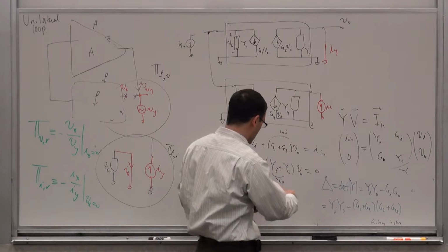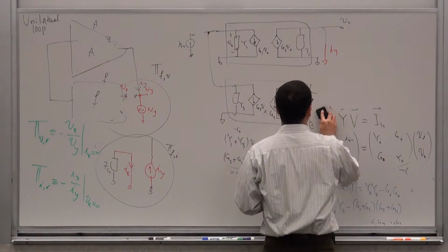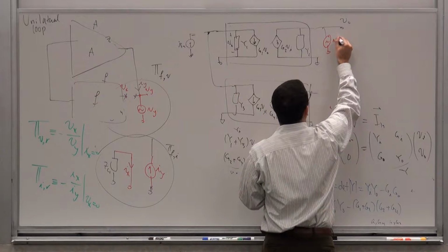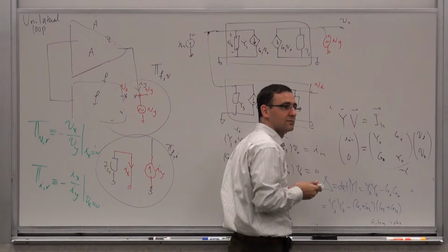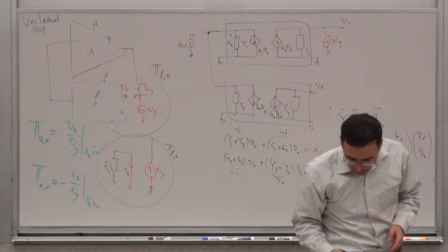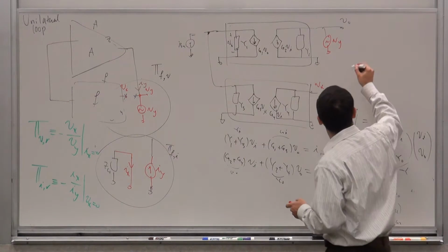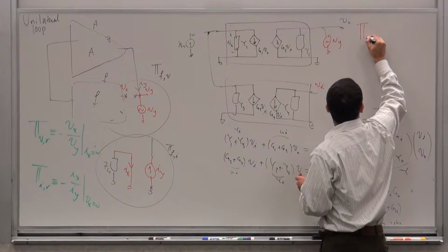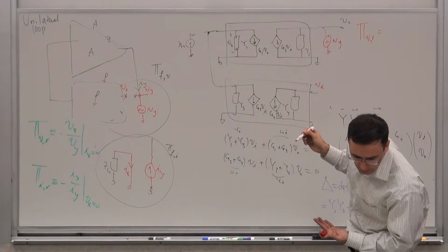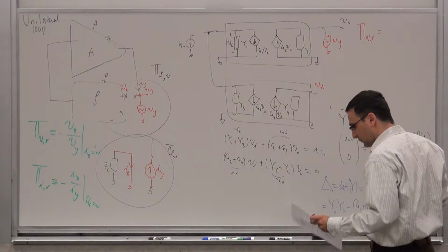It's a very similar procedure. If you want to calculate the reverse voltage gain, you've opened it here, but now you apply a voltage source here. So you apply a Vy here and measure Vx. And if you do that, you get basically a TVR, the reverse voltage loop gain, which you can calculate. You are writing the set of equations that we have.